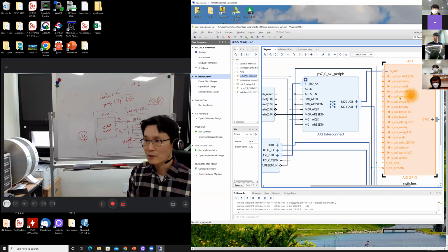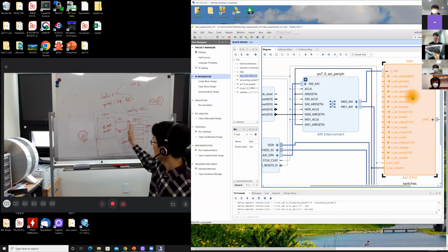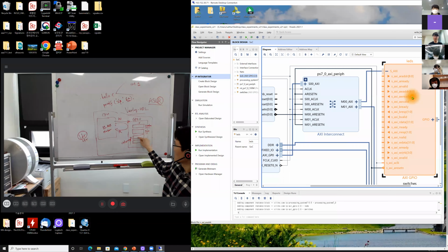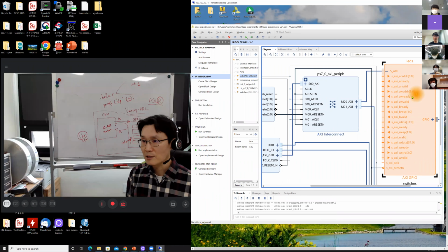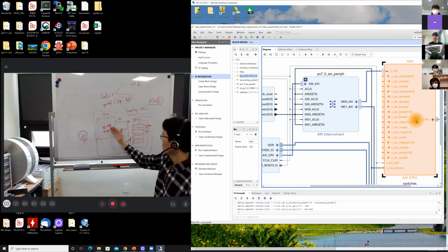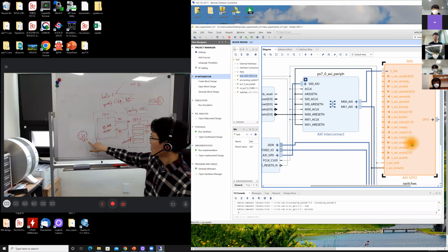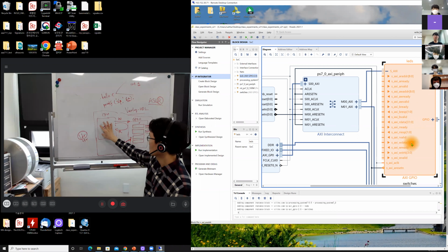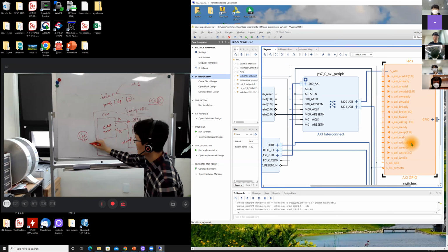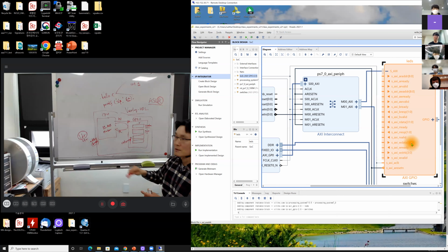When it comes to a write operation, if you execute an STR instruction, a store instruction, you are writing something to some location. So the write address contains that information. And read data: when it comes to LDR, GPIO responds with the data. Then write data: if you execute an STR instruction, the CPU should provide two things, address and data. You are writing this data to that location.